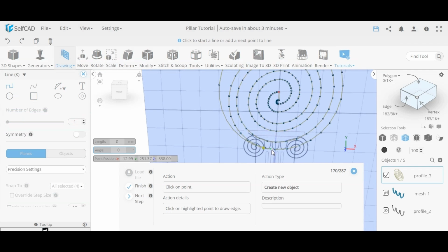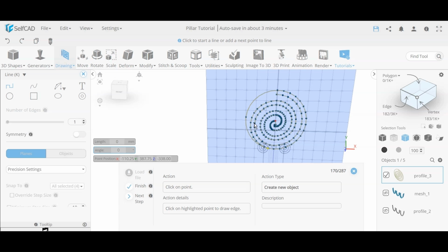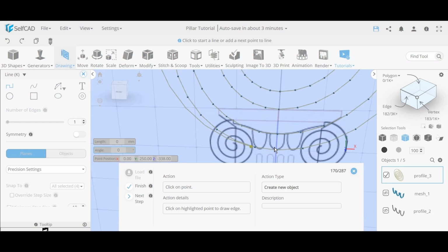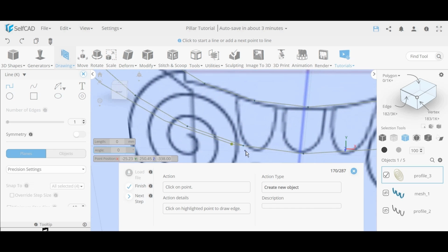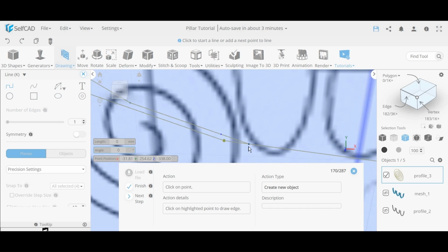So here is actually, until here we have the design. What it's doing now is not really part of design. It's a small thing, a technical thing, which is related to keeping objects manifold. So if you see what's happening over here, this is something very, very important. You see these come together at a single edge. So we have here two things that actually collapse at a single edge.